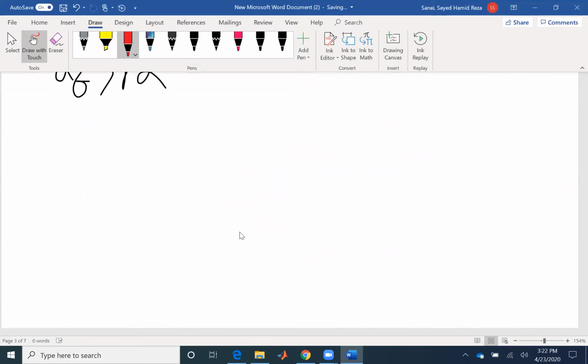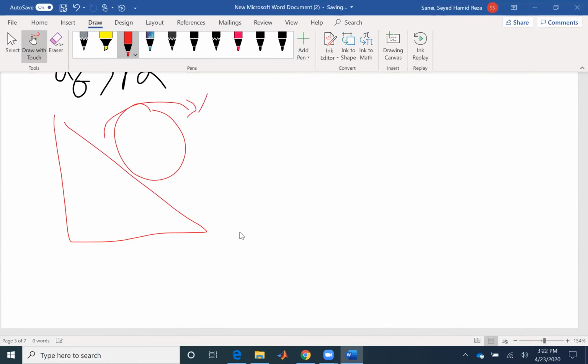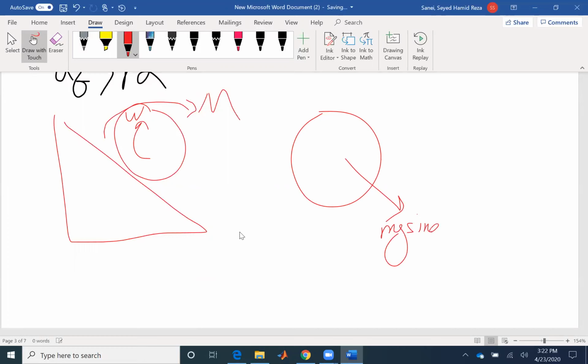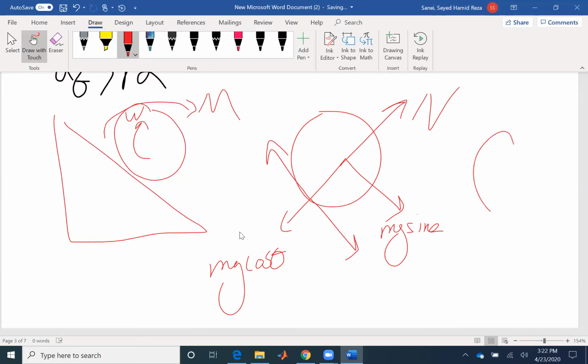Now let's look at another example, but this time we have an inclined surface and a moment m acting on our system. Everything is the same, it's just we have a moment. It's not just a pure rolling up and down. We have an external loading. And we have mg sine theta here, we have mg cosine theta here. We have n. We have a friction force that could act up or down, and the kinetic diagram, Ig alpha, and m ag.